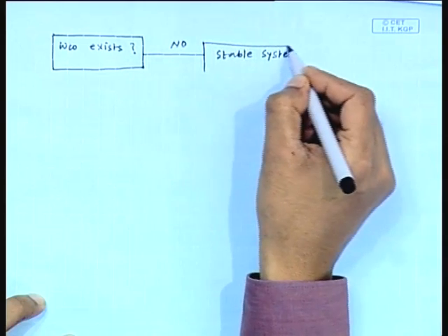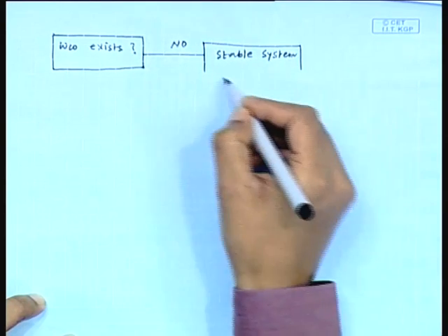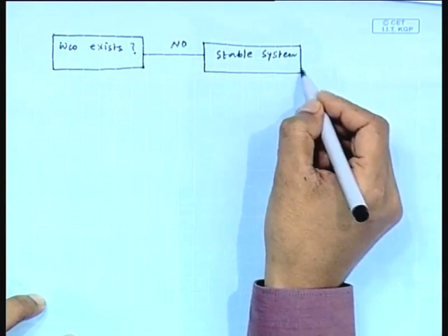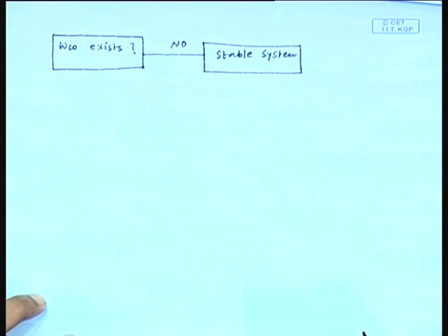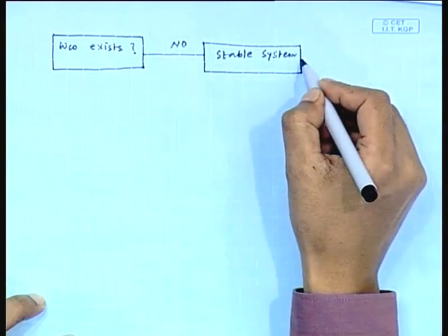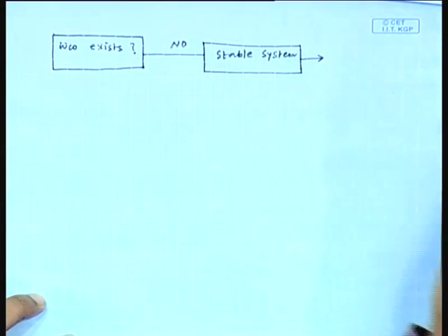If the crossover frequency does not exist, then the system is stable. So, you can use any Kc value, there will not be any instability problem, but as I mentioned, with the increase of Kc value, the response also becomes more oscillatory.